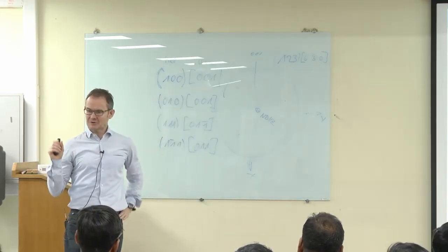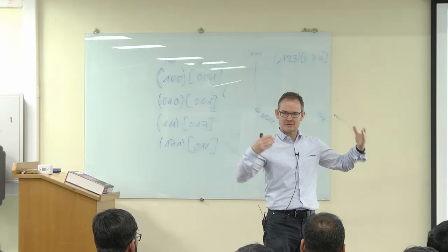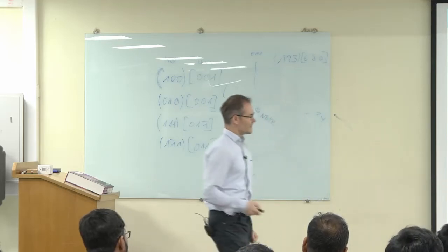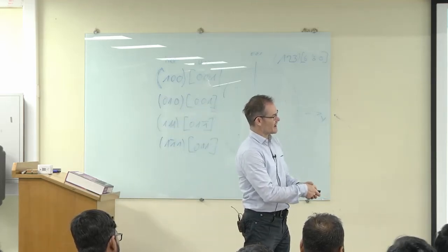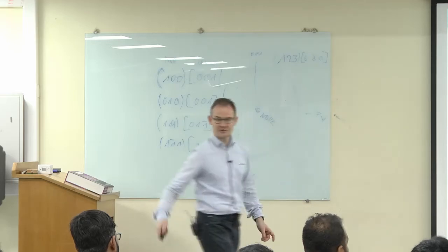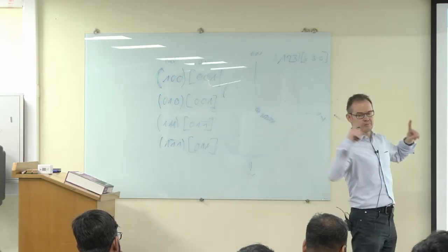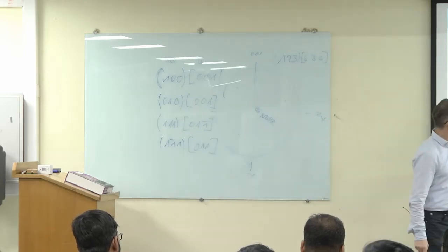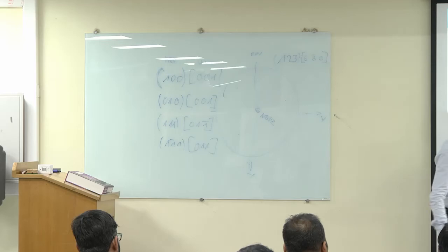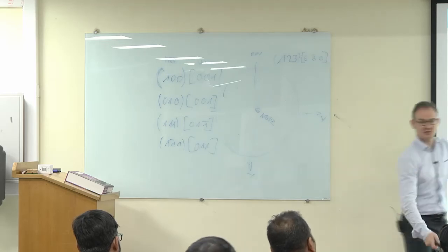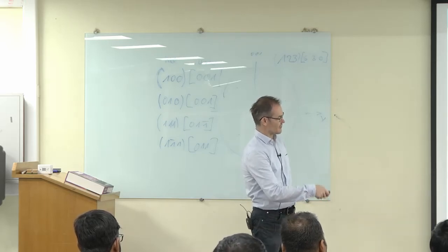So, and now comes a beautiful step forward. We can now say, okay, we can plot these inverse pole figures, and you will see pole orientation software does this. But we can now do another thing. We can assign the position in this triangle with a color. And we do this with a nice rainbow selection, which is here. That means whenever a pole is close to 001, we'll give it a color close to red. When it's close to 110, we'll give it a color close to green. And when it's 111, it's close to blue, and all the mixtures in between. And that means just by reading out the colors here, we are able to say where was this crystal.